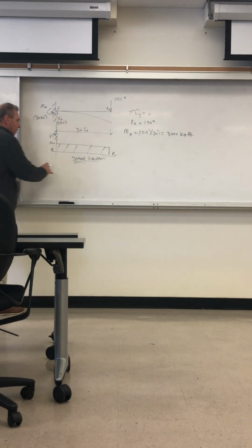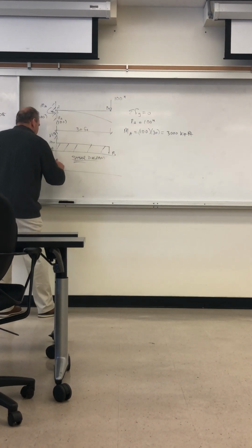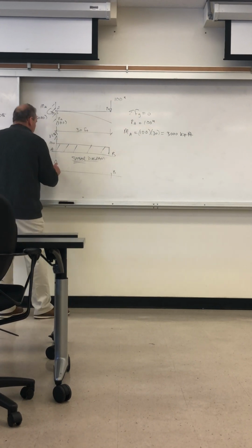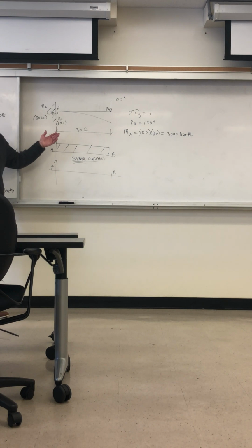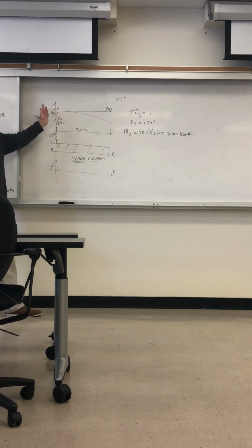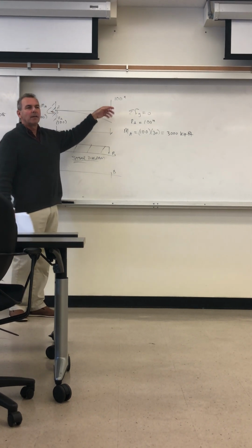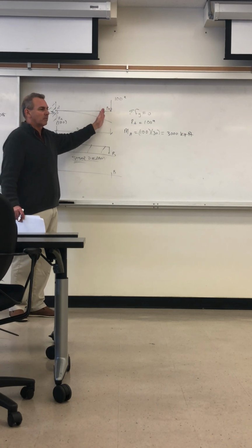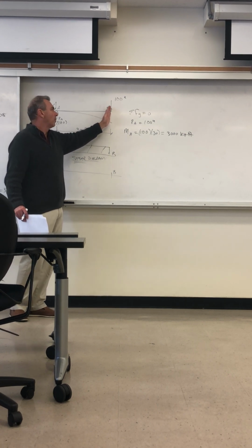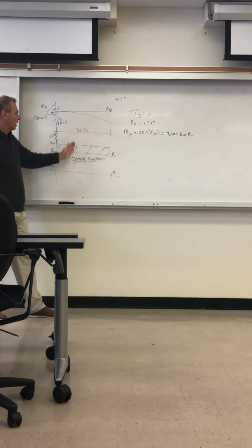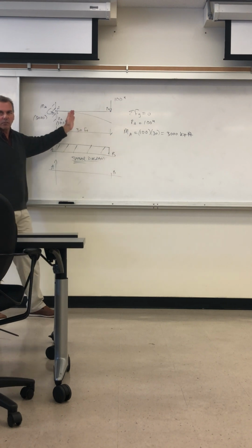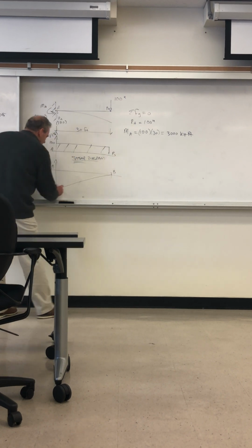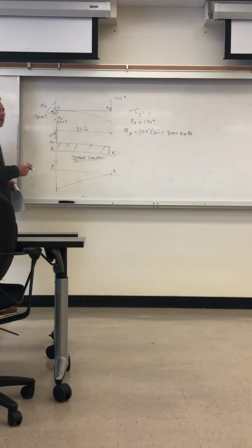Draw the moment diagram. So your maximum bending moment, where the structure would fail if you kept increasing this load, is right there. That's the moment increases. Zero here, there's a point load. So if you take, let's say, a differential distance to the left of the point load, the moment is the force times zero, right, or the dx. So the moment is increasing as you're going out, and it's linearly increasing with distance. So force times the distance, and it's the maximum. So the moment diagram is going to be triangular looking. This straight line, it's negative bending. The whole thing is negative bending.